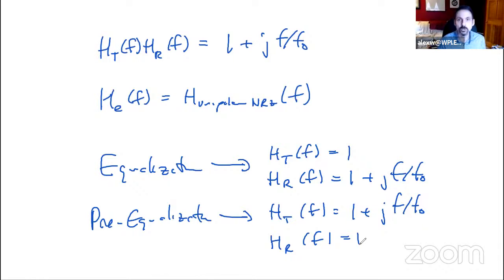All right. So lessons learned from this lecture. We looked at this idea of, first of all, rectangular pulse shapes, not so good in terms of bandwidth. Spectrally, they just sprawl from minus infinity to infinity. We looked at the concept of the equivalent filter, and how we have transmit filters and receive filters, and how we do equalization. Very importantly, we also looked at the concept of the channel and ISI, this smearing impact, and how it makes lives harder.